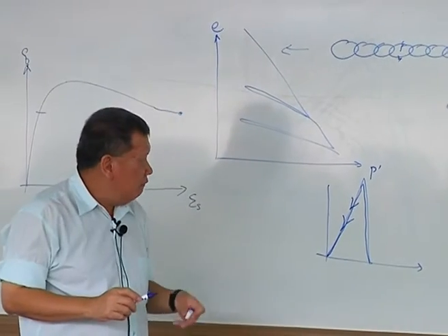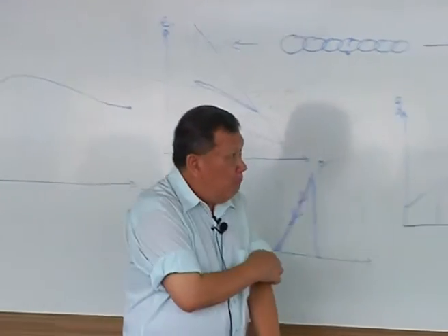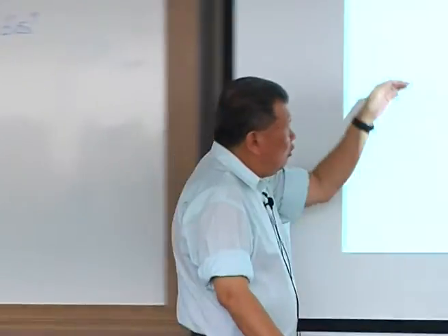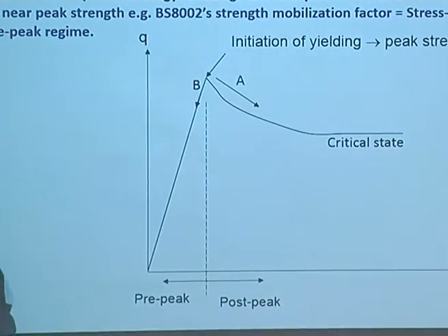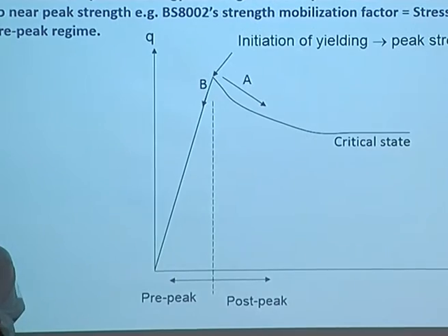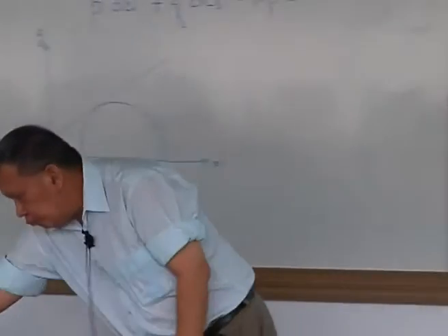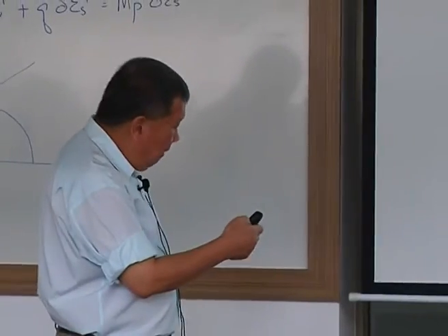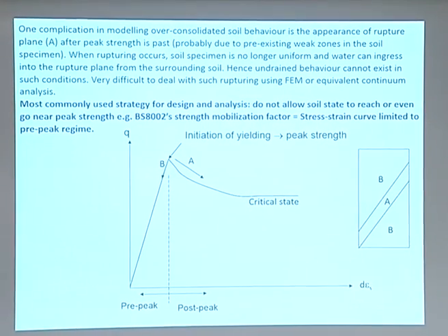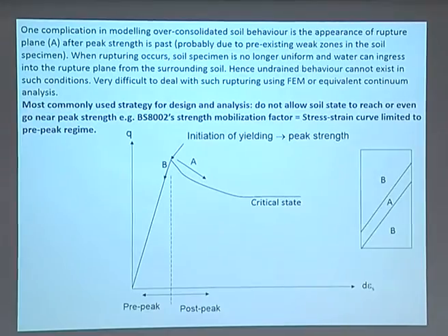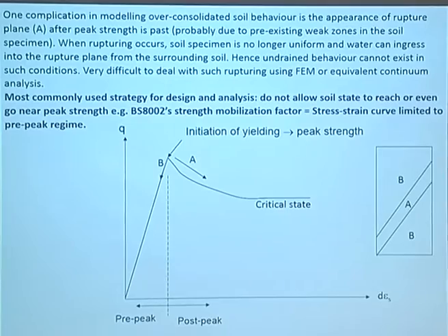So basically, this is an event that in soil mechanics, we call a bifurcation event. A bifurcation event is where part of the soil goes this way, the rest goes this way. You get what I mean? You got two eventualities, two ultimate situations. And the part that goes down the A path is actually the shear band. The shear band will continue to shear at increasing strain. But the rest of the soil over here will actually come down this way.